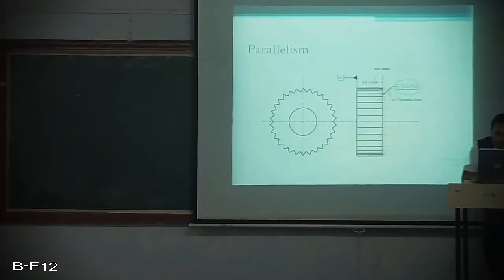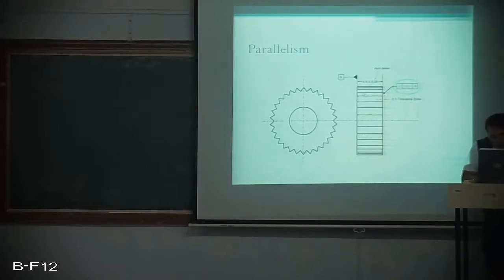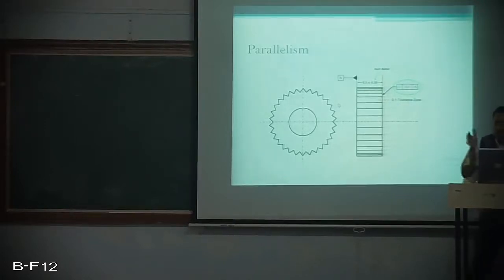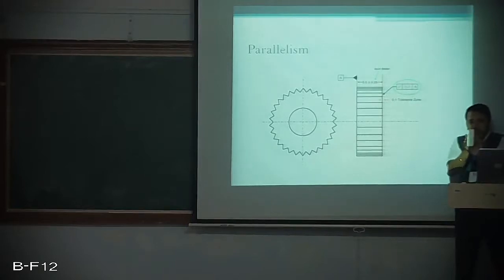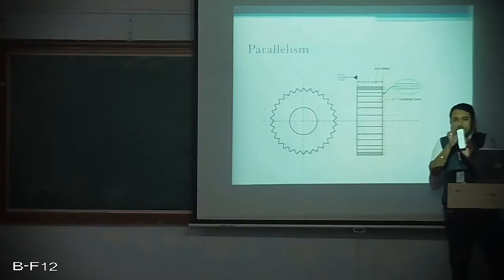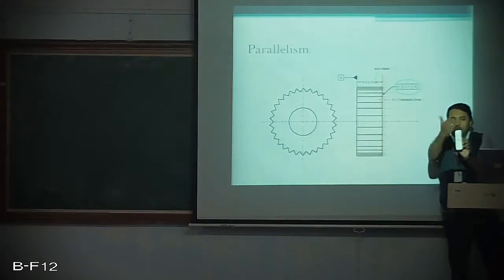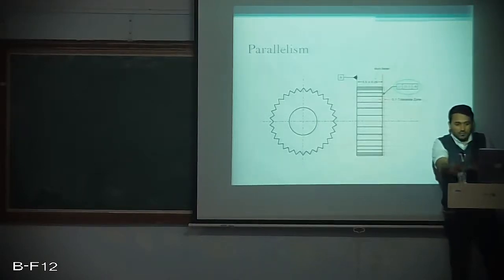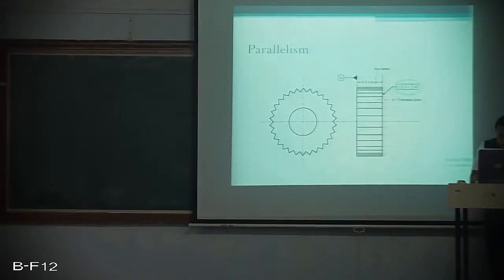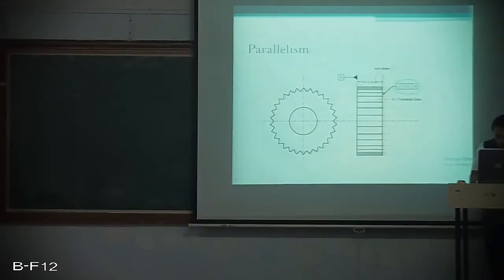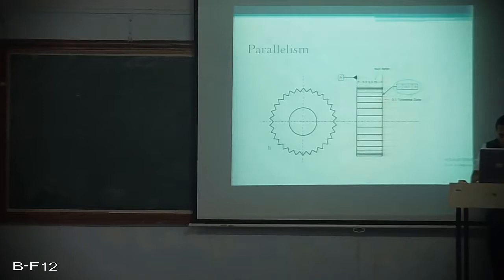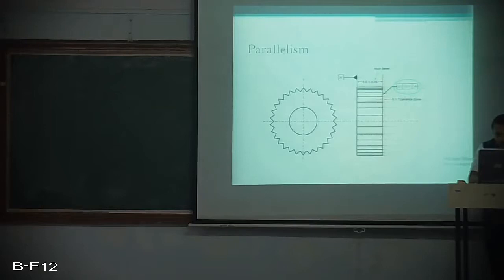Hence that is also indicated, but again what they are indicated, this was the gear with the tooth, this is a gear profile and there will be tooth on this, and this surface and this surface they want parallelism, and that parallelism is indicated over here, that this top surface and that bottom surface needs to be parallel, because the bottom surface they have taken as datum A and the top surface they want to be manufactured with respect to datum A and within the parallelism of 0.1. So that is how it is represented over here.